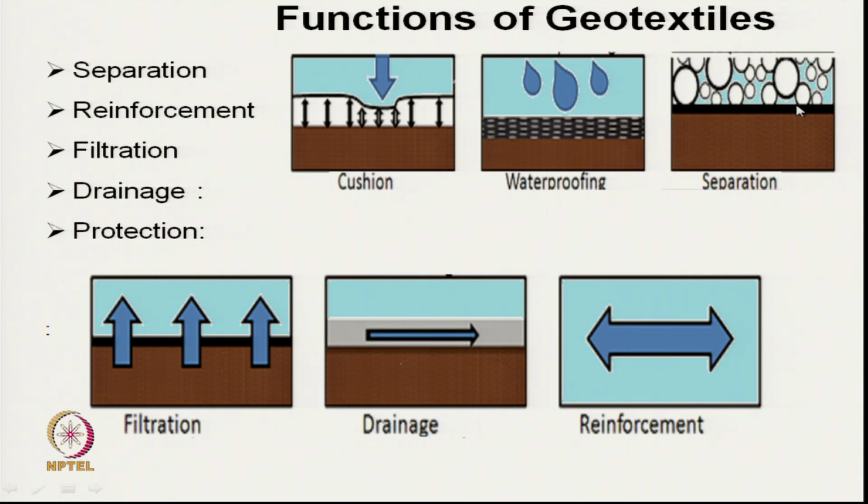If we do not separate this soft soil from the stones or gravels, the soft soil will penetrate inside this structure and will deteriorate the characteristics.